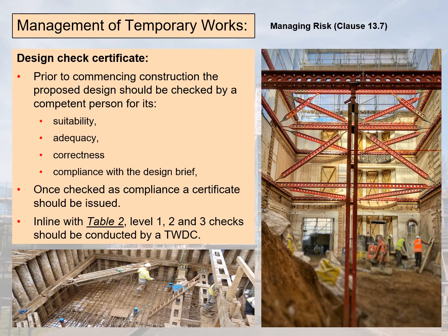To make sure that risks are controlled on site at the right level before any works to erect or deconstruct are conducted, the following checks need to be conducted. Does the design concept still remain workable within the conditions on site? Check the temporary works design for strength and structural adequacy, including the foundations and lateral stability, and is it robust enough? Things may have changed in the design since the initial brief was issued. Is the design still compliant with the design brief and is it still fit for purpose? So have things on site changed the facilities or the loadings or the stability of the temporary works against the original brief?